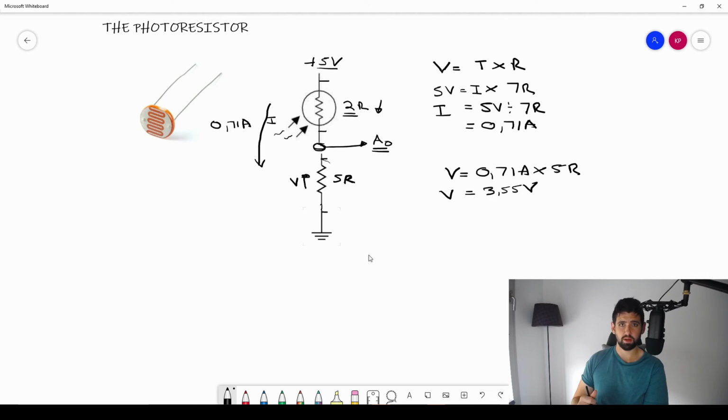So when I turn off the lights, my resistance will increase, my current decreases, so does my voltage, and then I can sense, okay, my Arduino Uno sees less voltage, that means it's dark inside or outside. Guys, I hope this was a nice explanation. As you see, we're going through tutorials. We'll get a bit more advanced because you guys are learning the basics so well. So let's move to the next section, and we're going to start putting all the stuff together.